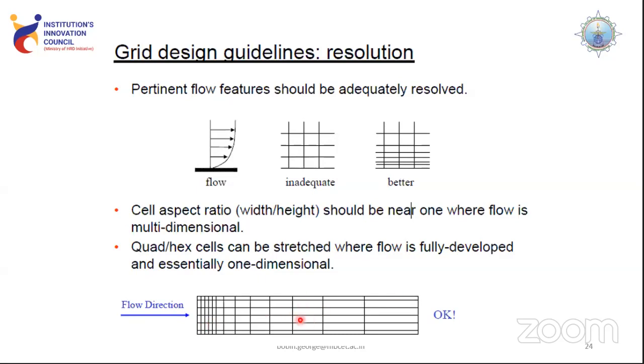Similarly, moving on to this computational domain, if the flow starts from here and there are no obstructions placed throughout the domain, once it enters the domain there will be a large amount of losses or changes associated with it. And these changes have to be captured in an effective manner. In that condition, the grids generated at the entry side have to be much smaller compared to the areas where there is not much variation. The application of these two types of changes we will look at in the application aspect.